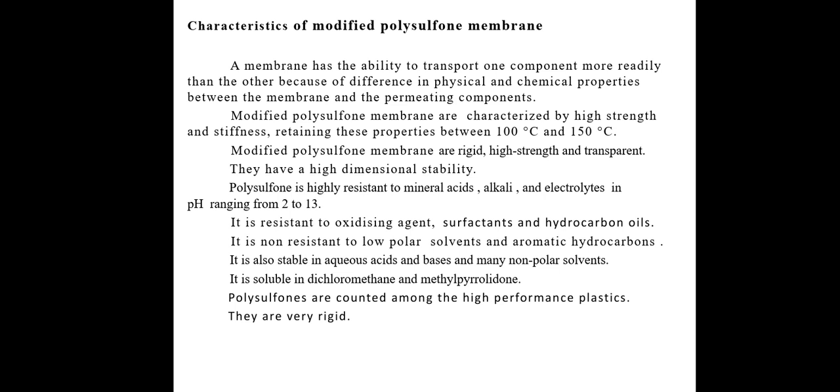It is also stable in aqueous acids and bases and many non-polar solvents. It is soluble in dichloromethane and methylpyrrolidone. Polysulfones are counted among the high-performance plastics. They are very rigid.